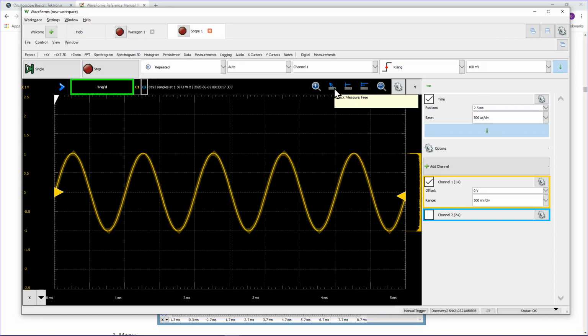Now, another thing that might be interesting is we want to take voltages off of this waveform at certain points to tell what the voltage is and how much time has elapsed. I clicked on this little cursor button, and it brought this interesting little cursor down so that it can see, even if I'm not on the waveform, it's telling you the voltage level, channel 1 colon 1.014, and this will take the voltage level for you.